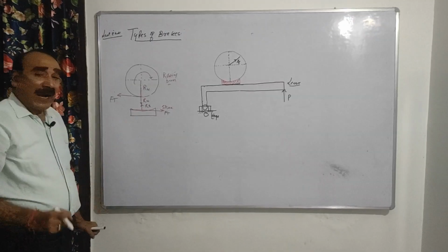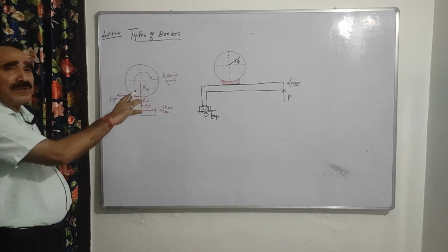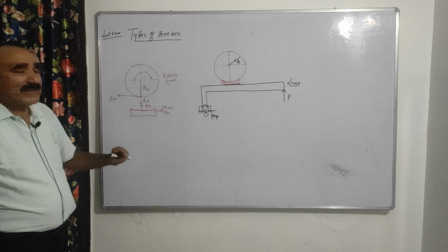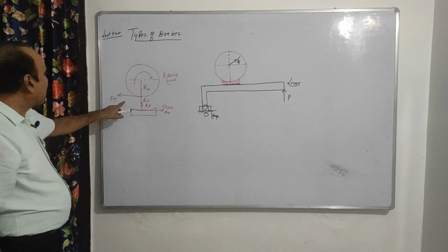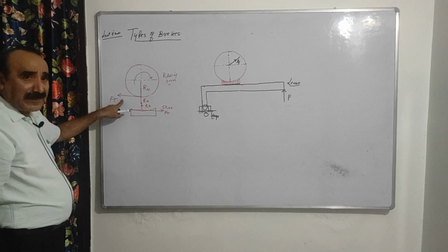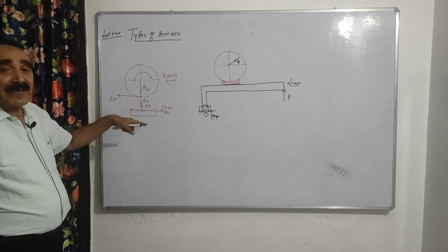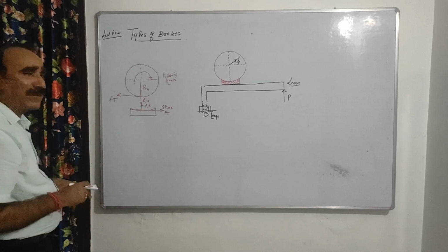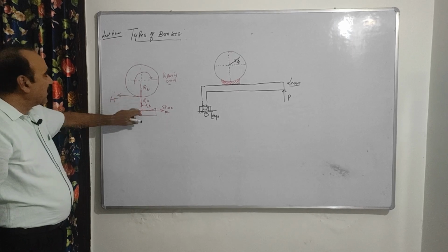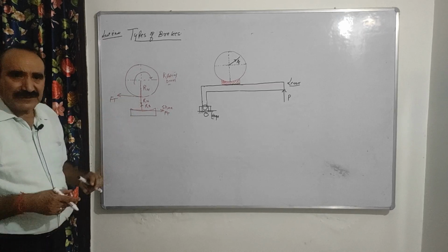After that, now I will take the working of this. This is all about how these forces act on the drum and shoe. And naturally, this Ft will create the torque at the center, which will retard the motion, and that torque is called the braking torque. This I will explain later on. But these are the forces. First you concentrate on the forces, that the shoe will apply these forces and the drum will apply these forces, right?